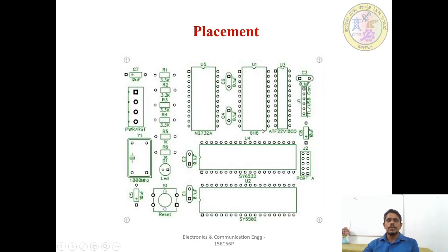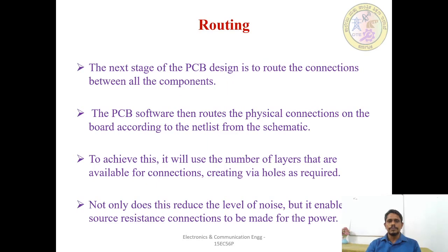This is the printout given by the engineer after placing the components. Once the placement has been completed, we have to give the reference PCB, or wherever the components are coming in your layout, to the engineer. He has to cross verify this, check and finalize this placement. Then only the PCB designer has to go for routing.